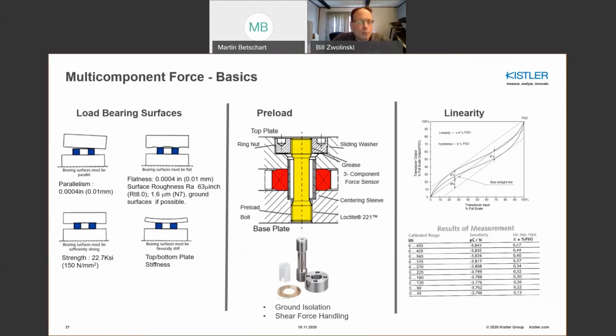But you might also want a few different calibration points, to use as a common platform for a variety of different tests. So now you can dial in a certain sensitivity for a given force range, and you get the benefit of the higher, better linearity as well, as illustrated here.